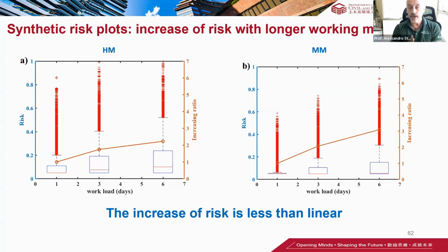Again, this is a useful tool to understand your duty cycle choices, so how many working days of dredging you want to do in a specific site. Intuitively, a lot of people think that increasing from 1 to 6, the risk can be 6 times higher. Indeed, the results of this analysis suggest, site specific of course, that the risk can be less than linear. So this is a good guideline for engineers to design a better dredging operation.